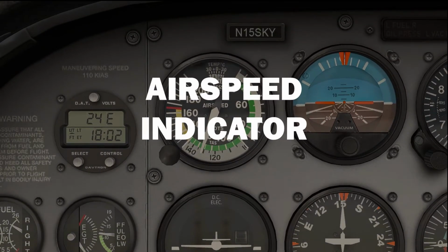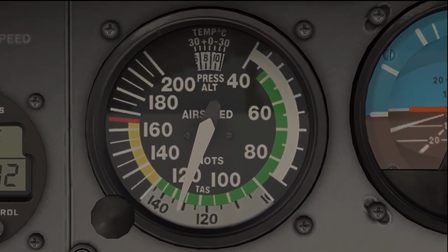Airspeed Indicator. This displays indicated airspeed, or how fast the airplane is traveling through the air. This is important because it tells you how fast the air is traveling under your wing. Too fast and the wing may become damaged. Too slow and the wing loses lift, causing the airplane to stop flying.